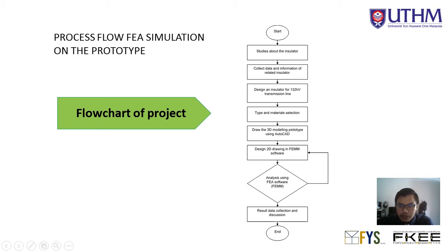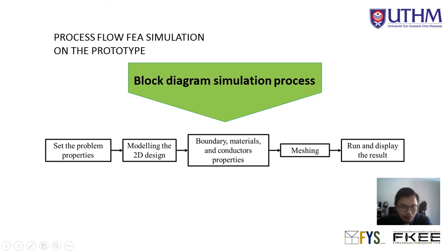Then we design the insulator using AutoCAD in 3D modeling, and we design the 2D drawing in the FEMM software to analyze the voltage field and electrical field. If the analysis is successful, we proceed to data collection. If the analysis is not successful, we return to the 2D design and redesign the insulator until we get the proper result.